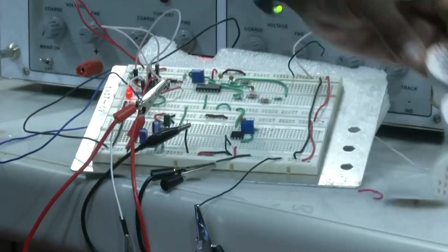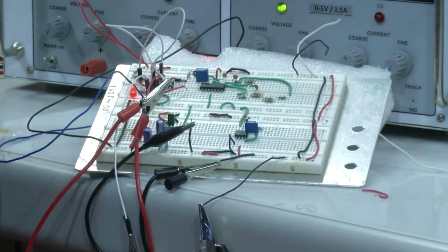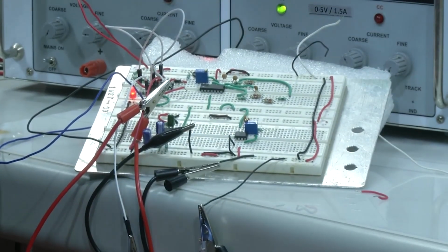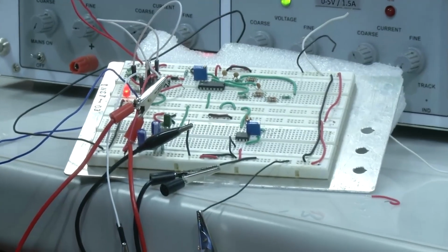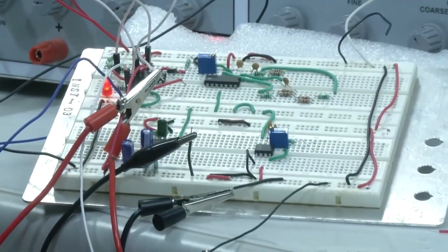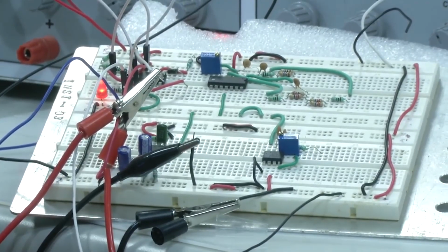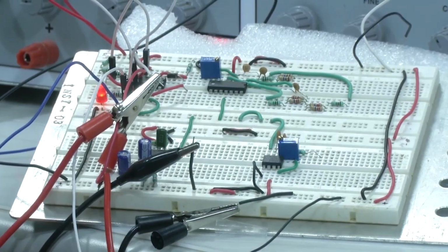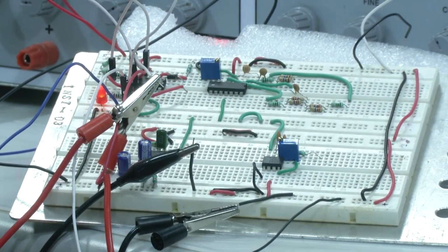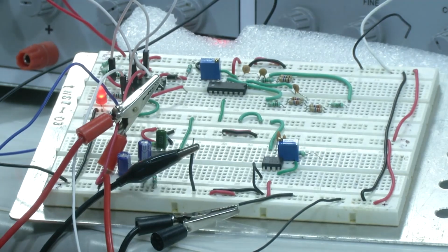Then we will pass it through the amplifier for amplification of the ECG signal. Unless we do the amplification, it is very hard to detect using our normal DSOs, because the amplitude of the actual ECG signal is very poor. So, in order to improve our signal ratio, we pass it through the instrumentation amplifier, then through filtering, so that we can easily visualize whether the signal has been filtered or not.